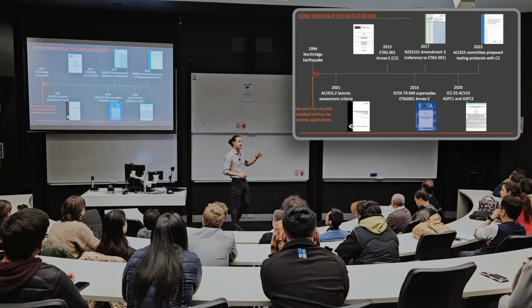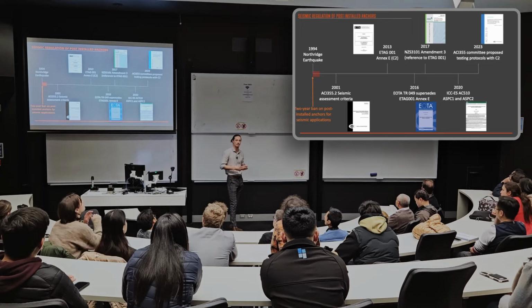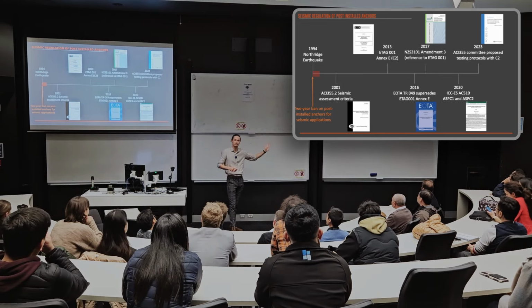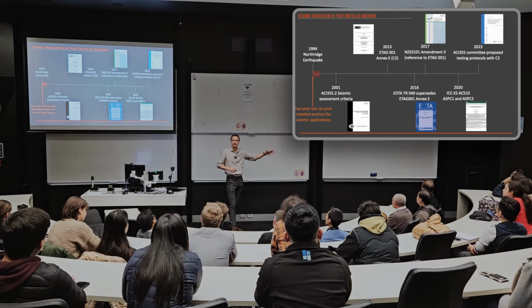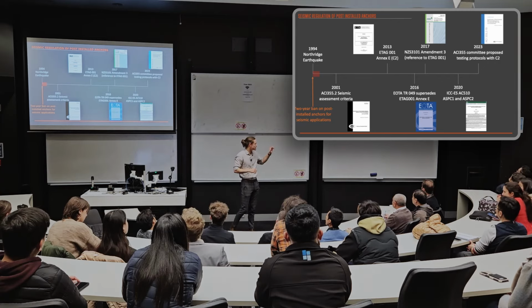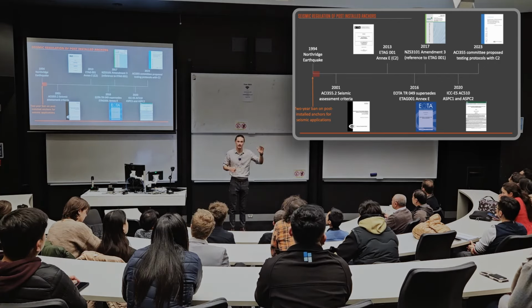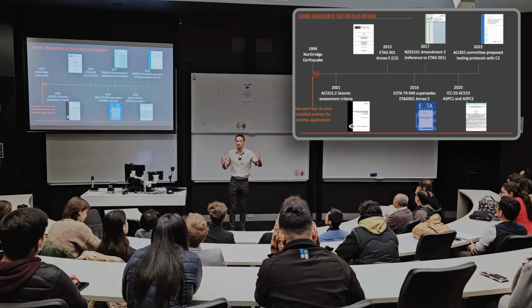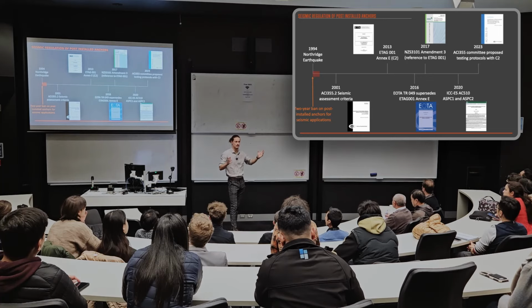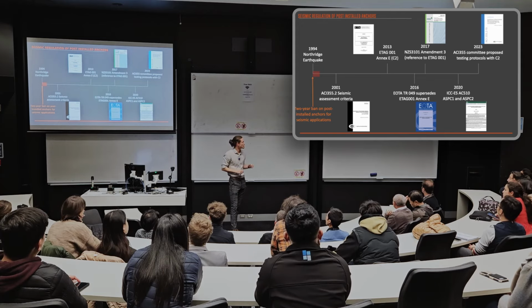It wasn't until 2013 when the Europeans came to the party and published what we're mostly familiar with in New Zealand, those kind of C1, C2 guidelines. C1 is really heavily based off the ACI 355 guidelines. They really took that and they added this C2 criteria above that for higher levels of seismic loading. Now, in 2016, Annex E, which is the criteria for C1 and C2, was actually technically superseded. The correct reference is now Technical Report 049. It is essentially the same document. They just restructured how they did their codes, but it's a good thing to be aware of.